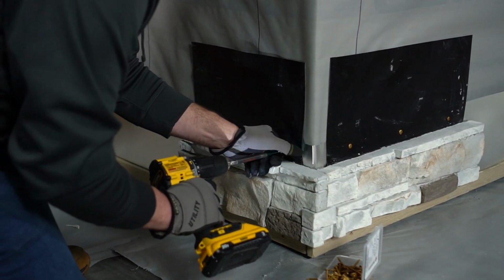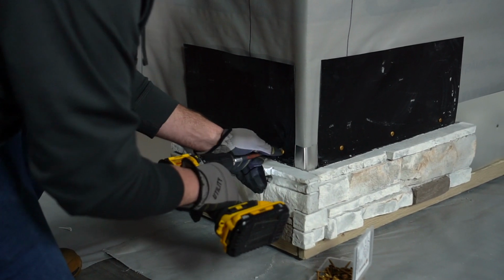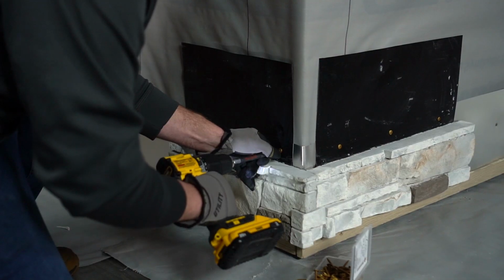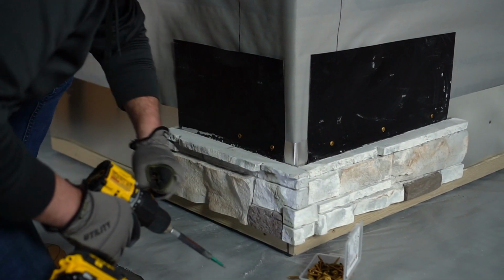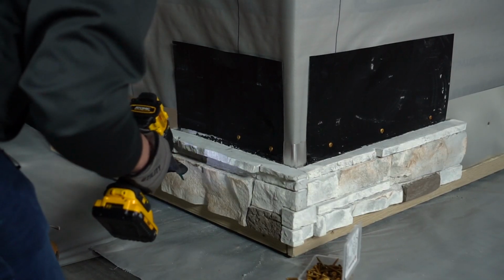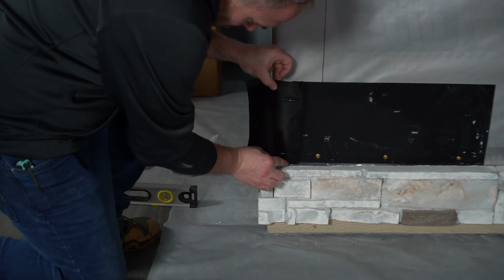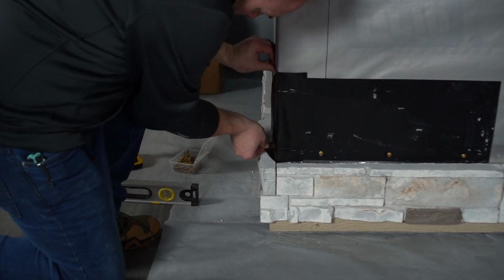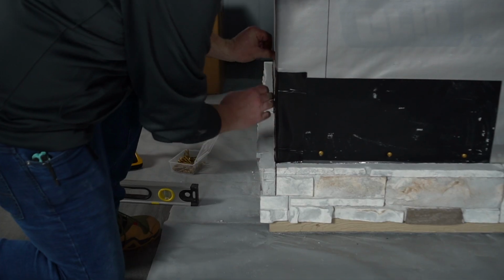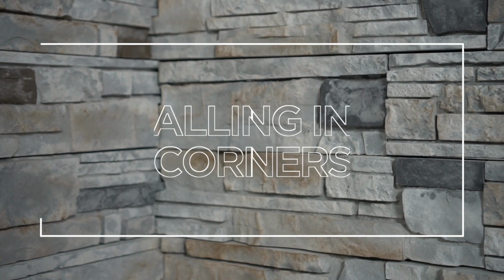If the corner of the frame wall is not square, you may want to use some composite shims to adjust the corner fitment for a better alignment and appearance. You will notice that the flashing for the panels do not overlap as the flat panels do. In this application, cut and adhere a piece of self-adhered flashing, SAF, over the integrated corner flashing, covering the exposed corner. Do not screw through the SAF, as this could allow water to get behind the assembly.